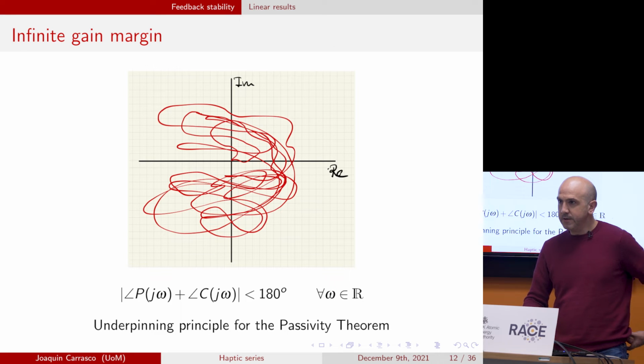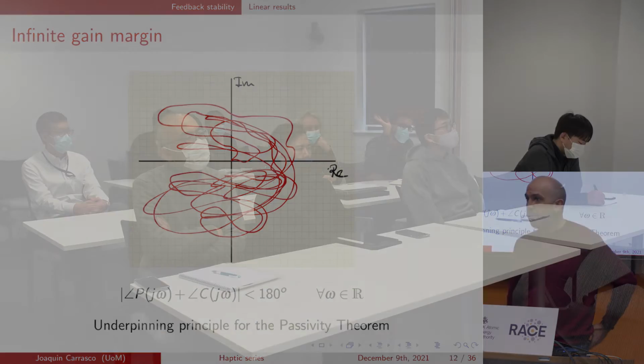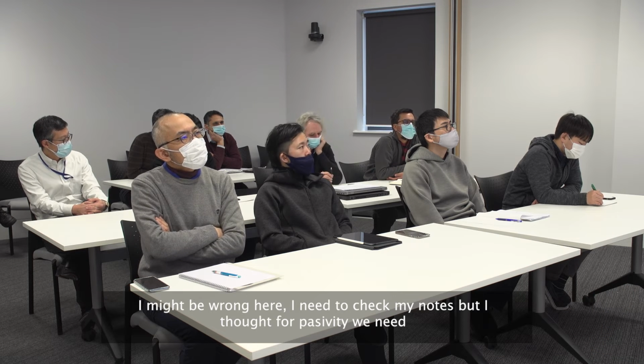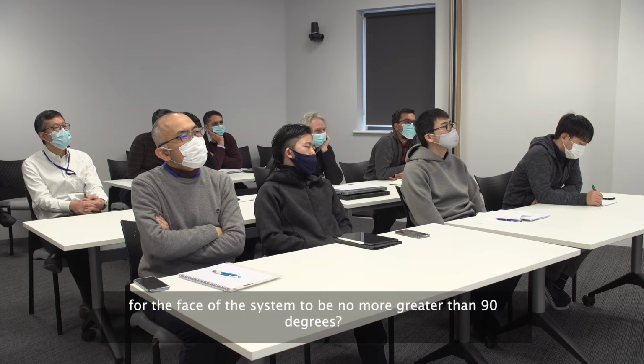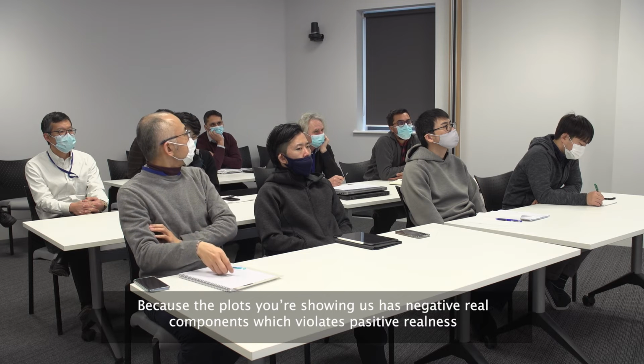Any question about this? Yeah. I might be wrong here. I need to check my notes, but I thought for passivity we need the phase of the system to be no greater than 90 degrees, because the plot you're showing us has negative real components, which violates positive realness.